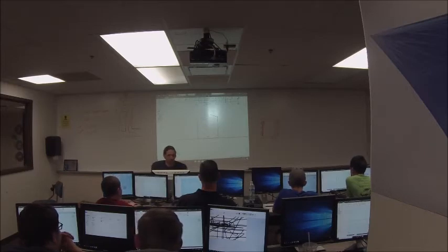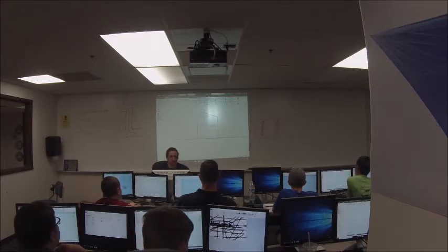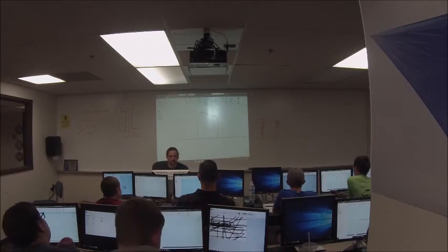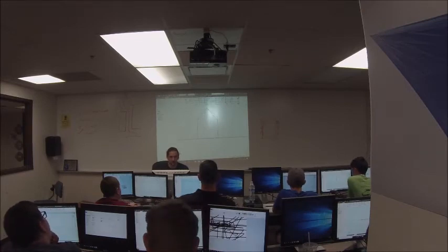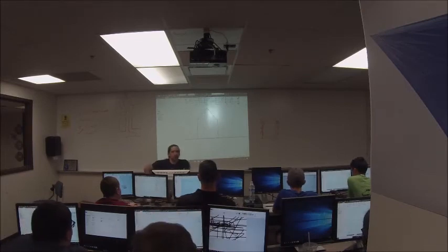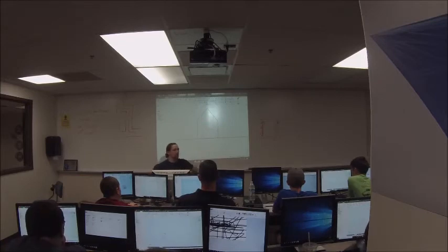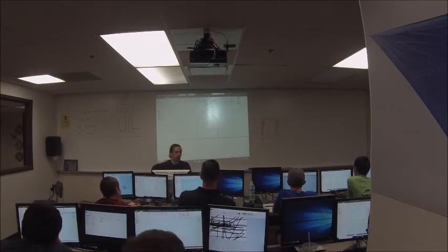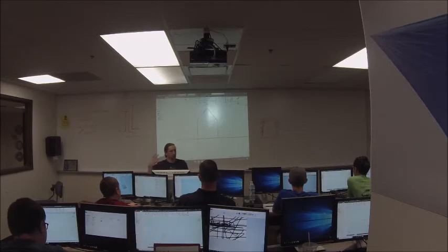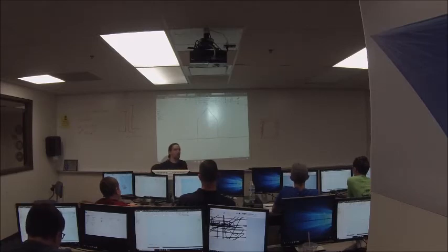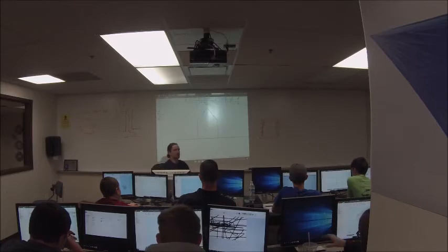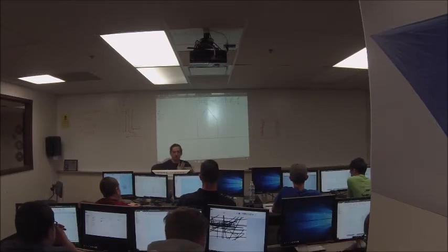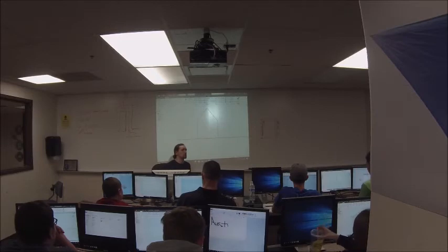So now if I wanted to, I could pick a different line. I could turn this into a completely different shape if I wanted. Hide my constraints, right? Make a little house shape, whatever I want to do. So if you're editing a part that's already been modeled and you need to do something crazy where you need to add some geometry to it, or if you want to start with a basic shape and then change it to make a more complicated shape, you can throw a rectangle in there and take the rectangle apart, so to speak, by deleting coincident constraints, deleting horizontal constraints and such.